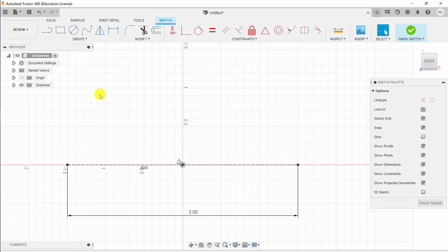Now, we need our vehicle to sit on some sort of pedestal, which is going to be used to generate the enclosure. We can't have the car terminate in a circular wheel because Space Claim doesn't let us generate an enclosure around the vehicle if we have the bottom of it terminate in a wheel shape. So we need to basically sit the car on top of like a pedestal. And the way that we do that is we just generate 2 rectangular structures where the wheels would go, and we have the vehicle sit on them. So we're going to do that right now.